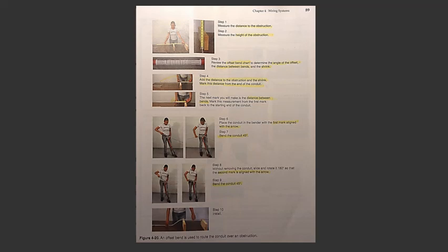Look at the offset bend chart to determine the shrink and the distance between the bends. Add the shrink amount to the distance you measured in step 2. Place a mark on the conduit at this calculated distance. Take the distance between bends found in step 4 and mark the conduit back from the first mark.